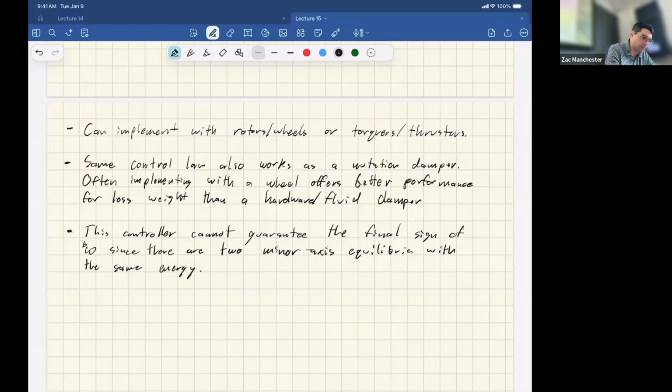And then I can slightly rewrite this as that same R crossed with what I'll call A, which is going to be the thruster axis unit vector. So we've got the offset from the center of mass where that thrust is applied. Then we've got the direction the thruster is actually pointed, right? And so the cross product of those two things gives me the torque from the thruster. And then this is times the actual U, which would be the thruster command.